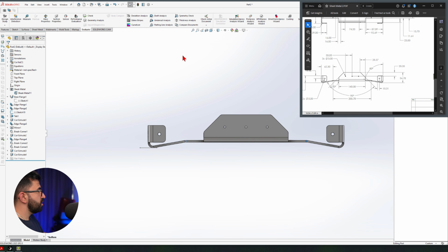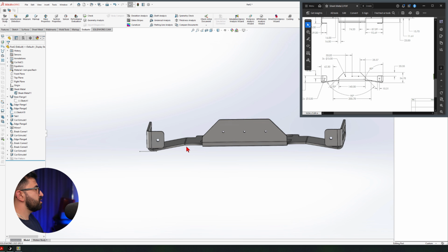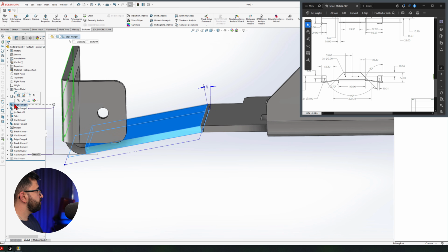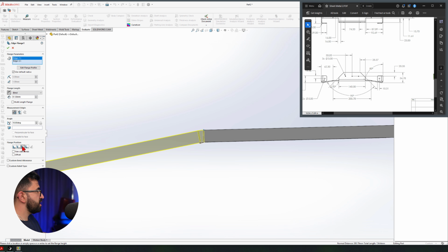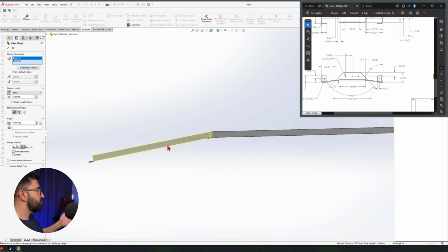So why do I have this issue? I know why. Because I changed this one, and I brought it in. This is the issue. Instead of having it like that, I have it like that. So if I move it out, then I'm just extending that 62.31. So I'm going to reduce it here. Let's just do 60 and measure again.